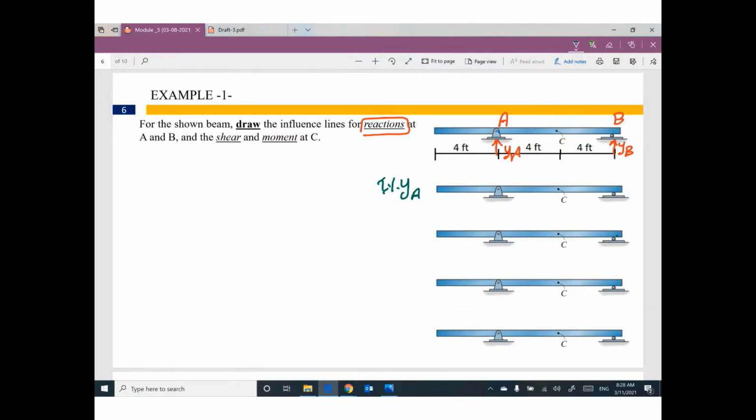Three steps. Move, keep, the resulting deflected shape. Move support A up by 1, so the new location of this beam is up by 1. Any other support? Yes, we have this one. Please keep it without movement. The new shape of this stick will be like this.